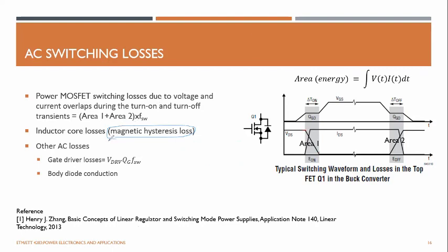I'm not going to discuss that in detail, but in practical scenarios, the inductor is heating up due to its DC ESR, as well as the losses of the core. The core loss is hysteresis loss. If you use an air core inductor, there's no hysteresis loss. But if you use a ferrite core or soft iron, there's always hysteresis loss.